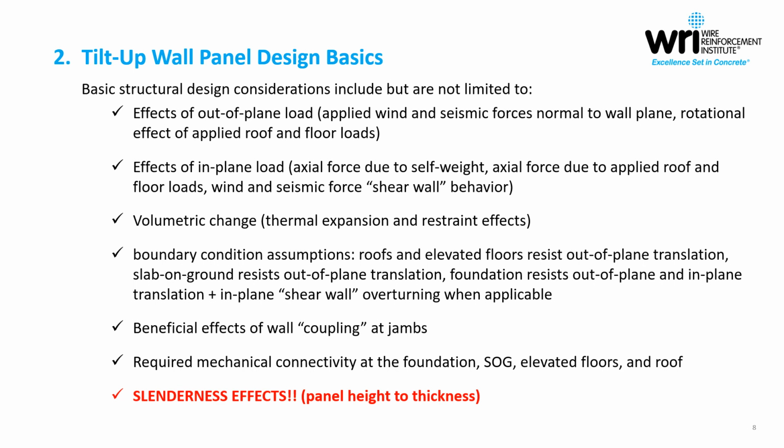Volumetric change is another thing, so thermal expansion is a pretty significant consideration, along with the restraint effects. How are panels connected together? What does that connectivity look like at the corners? So volumetric change is something that we do need to pay attention to as designers of tilt-up wall panels.